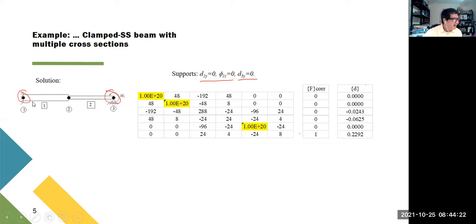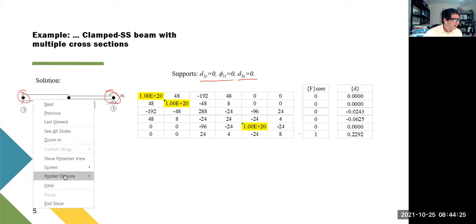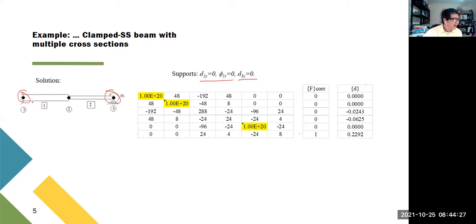Anyway, you can see that the deflection will be like this, then go downwards, and they have to go up like this. Okay, so we see that the deflection here, because of the moment, has to be negative downwards. This is what we see here, negative, and rotation is going to be negative. And on the other end, the slope is going to be positive. So this makes sense with that.